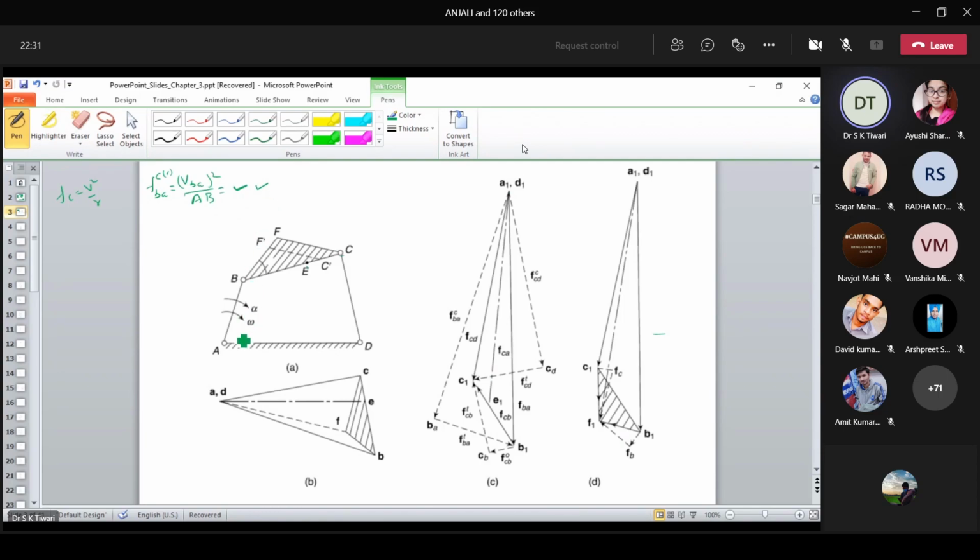It will be parallel to this link through the center of rotation. This is the center of rotation A1. You know the magnitude. Choose a scale for drawing the acceleration vector. Place your drafter with one arm parallel to this, the other arm will be perpendicular. Here I do not need to do anything with perpendicular right now, only parallel. Come to the center, draw a vector. This vector is drawn parallel to this particular line, and this represents the centripetal component of acceleration of B with respect to A. This is the direction of the arrow. Clear? Yes, sir.